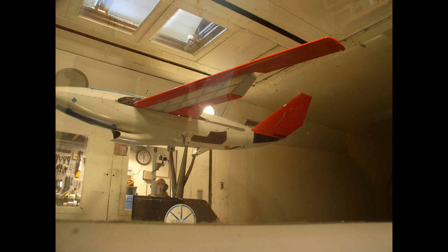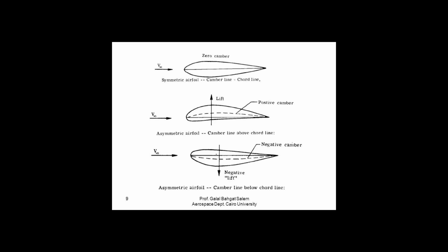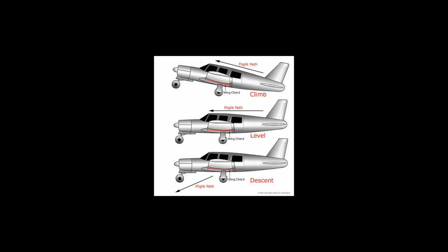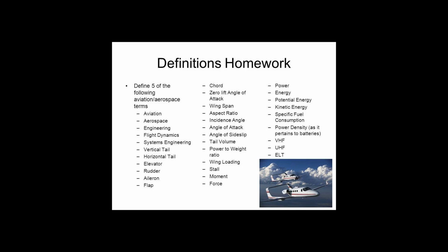The ratio of the length, or span, of a rectangular planform wing to its chord is known as the aspect ratio, an important indicator of the lift-induced drag the wing will create. For wings with planforms that are not rectangular, the aspect ratio is calculated as the square of the span divided by the wing planform area. Wings with higher aspect ratios will have less induced drag than wings with lower aspect ratios. Induced drag is most significant at low airspeeds. This is why gliders have long slender wings.